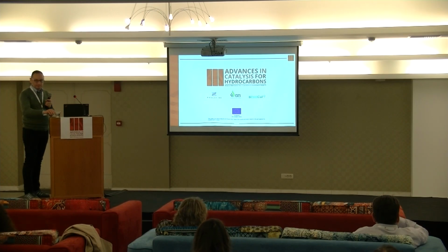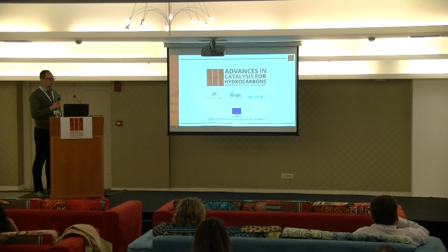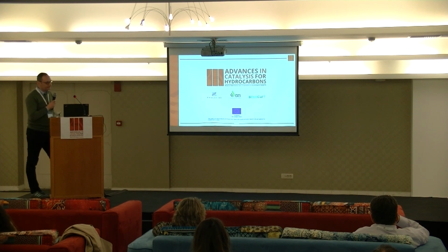Before leaving the stage, I have an open question for you. Apart from DEA, which other amines have you used? During the project, we have experimented with pure water, which does not give meaningful carbon dioxide removal values, because it's mainly a physical absorption case. We have used monoethanolamine and methyldiethanolamine.